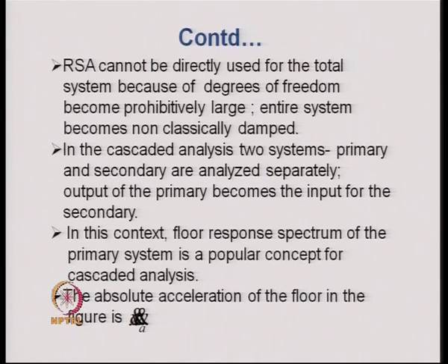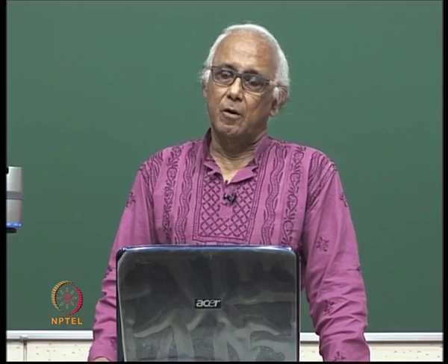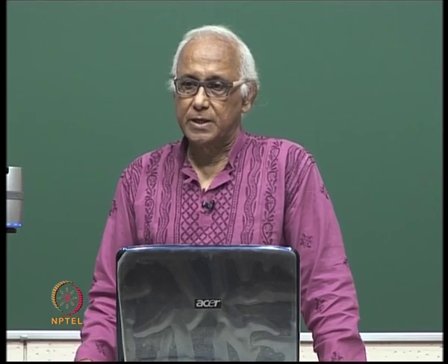This time history of absolute acceleration then becomes input for the piping system, which is mounted on the floor. We assume that the piping systems are attached to the floor in a way that one can assume the ends or the supports of the piping system to be fixed.